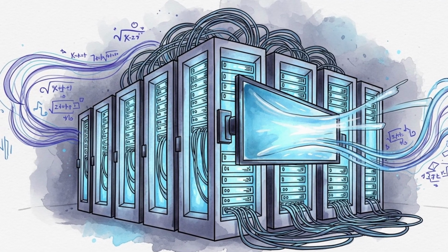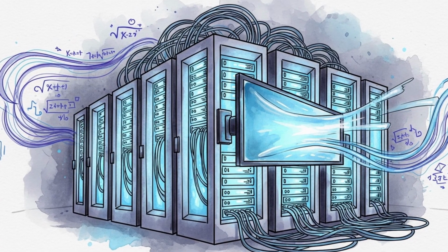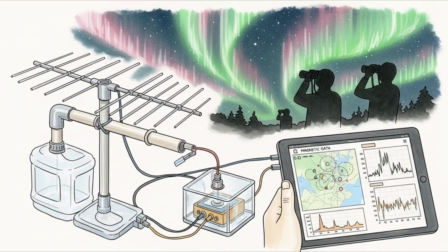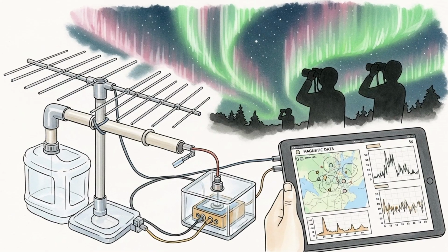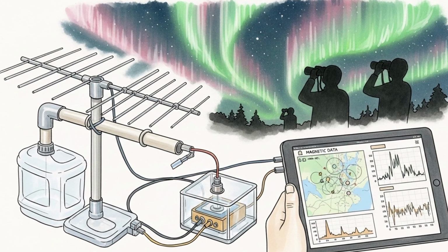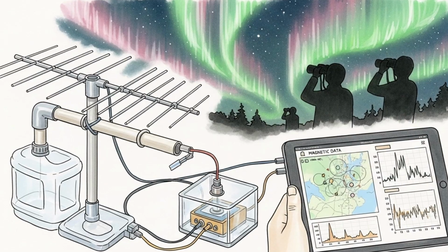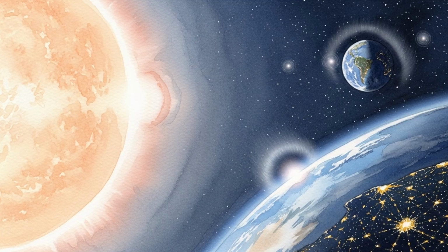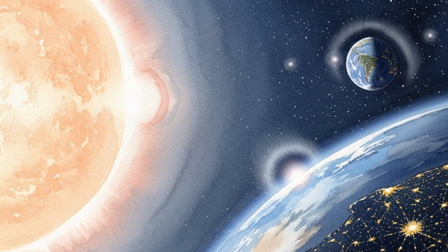Mission design includes radiation quiet zones and storm shelters. In low Earth orbit, water tanks, food stores, and equipment are used to add mass around a small area for temporary shelter. For beyond LEO missions, dedicated storm shelters with higher aerial density are planned. Vehicle timelines include safe mode attitudes that reduce exposure from trapped particles by minimizing time in the South Atlantic anomaly when possible. Health management follows established occupational frameworks.